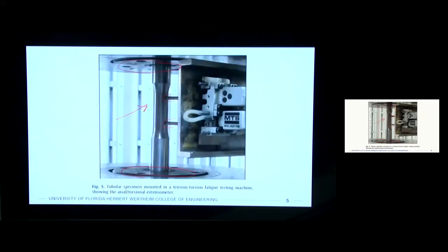And these are the extensometer. Okay? So they don't contribute to the load that's felt on this because the loads applied are much higher. But what it does is it measures the distance between those 2 points in space. And so that is a very precise extensometer that can fit onto the load frame and continuously take data at the same time as the force data is being recorded.